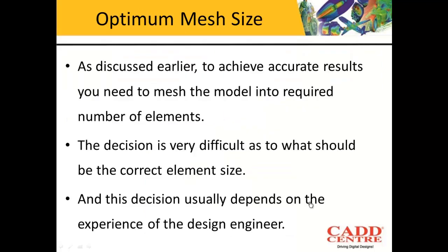Now, how do you decide what is the optimum mesh size for your analysis? It is very difficult to understand what should be the optimum mesh size, what should be the effective mesh size for my analysis. When we are performing an analysis, if we keep on refining the mesh, your answer will become much more accurate. But as we are refining the mesh, the time taken for the analysis also increases.